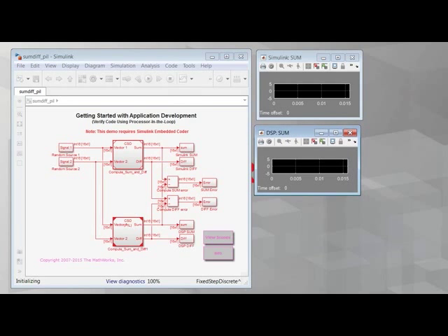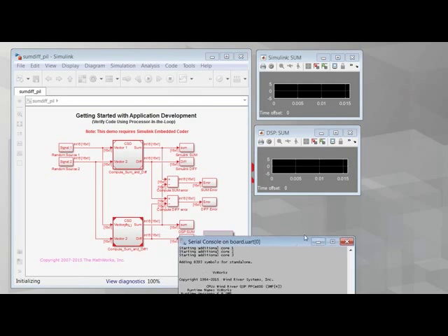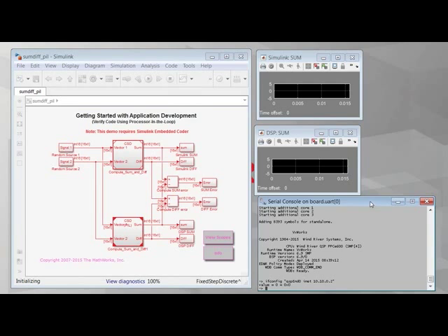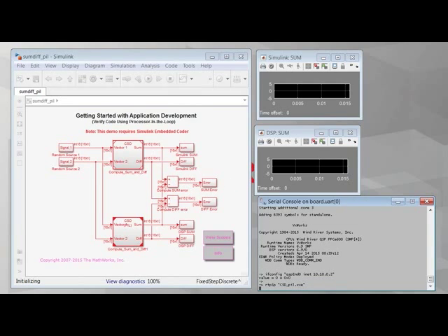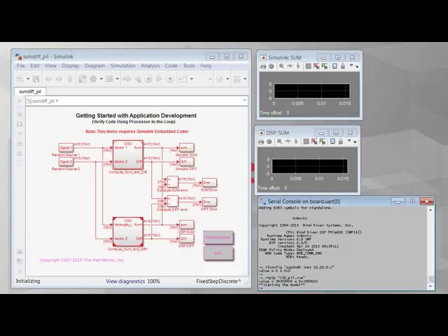The process is similar. When I click on Run, Simulink will generate code, but then link that, this time, into a VxWorks downloadable module. Simics will then create a virtual board, boot VxWorks from Flash, which will then FTP download our compiled image. When that image containing our controller code starts, Simulink will communicate with it to complete the controller to plant model communications, and thus completing the PIL loop.